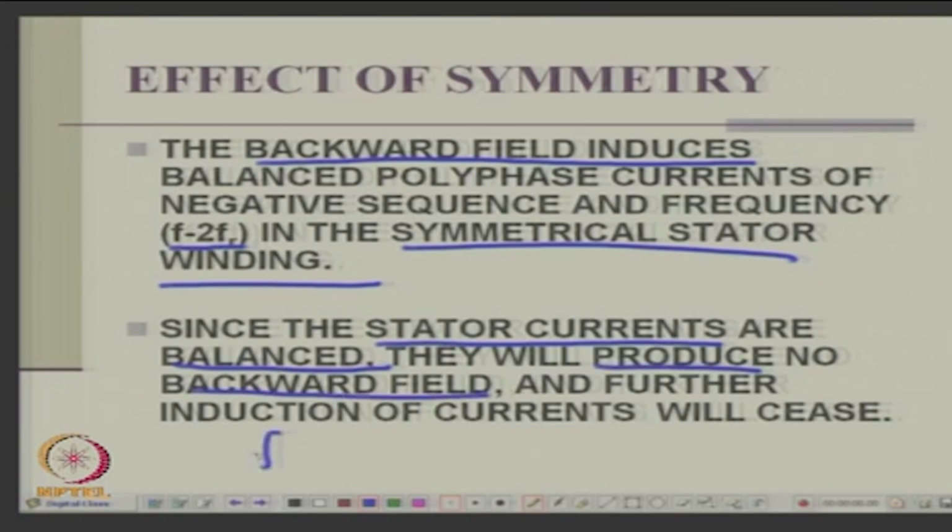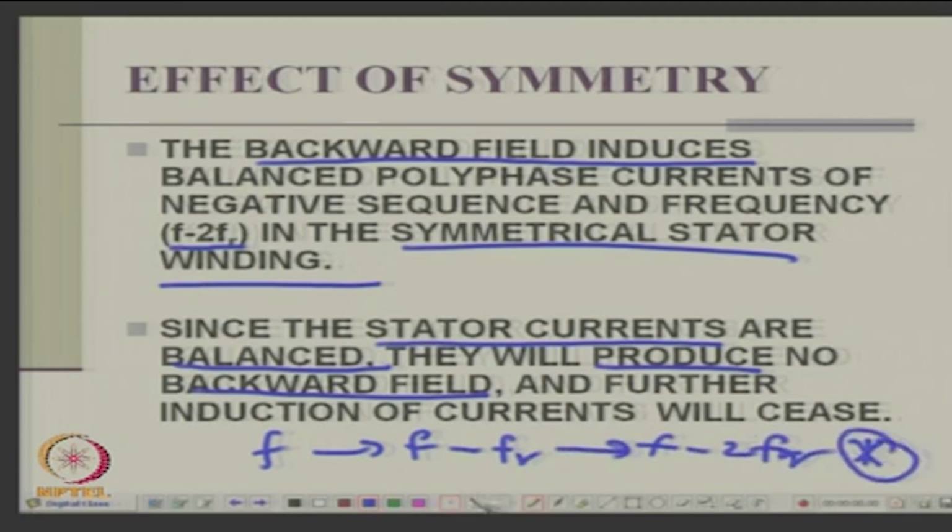So, there will be F here, F minus Fr here, and then F minus 2 Fr, and then it will stop. So, there is no further induction of currents in the rotor beyond this.